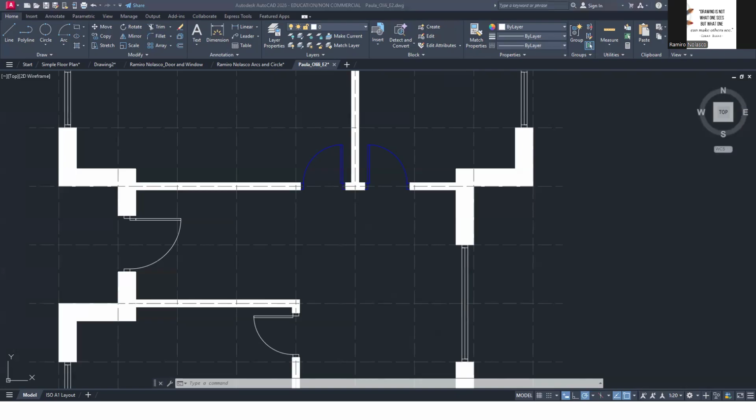Sorry, do you mind me asking you about this? So I selected everything for the window, but I want to color it, but the window here says windows are white. Just click window, and then go to the layer command, LA layer, and change the window color.